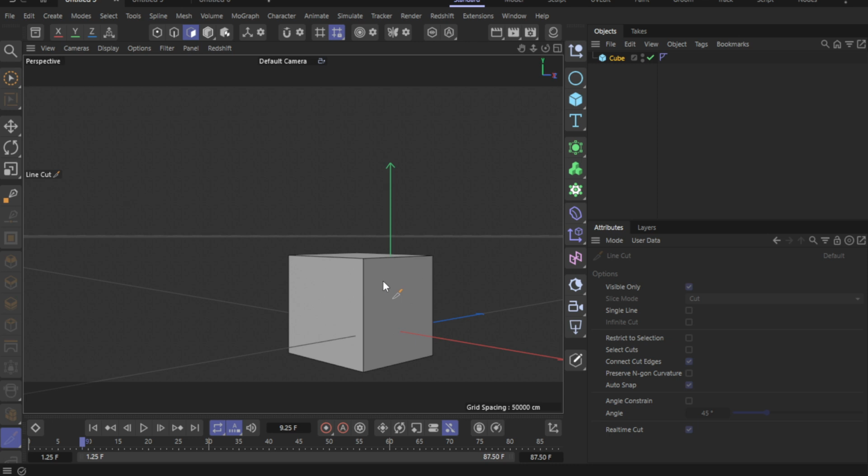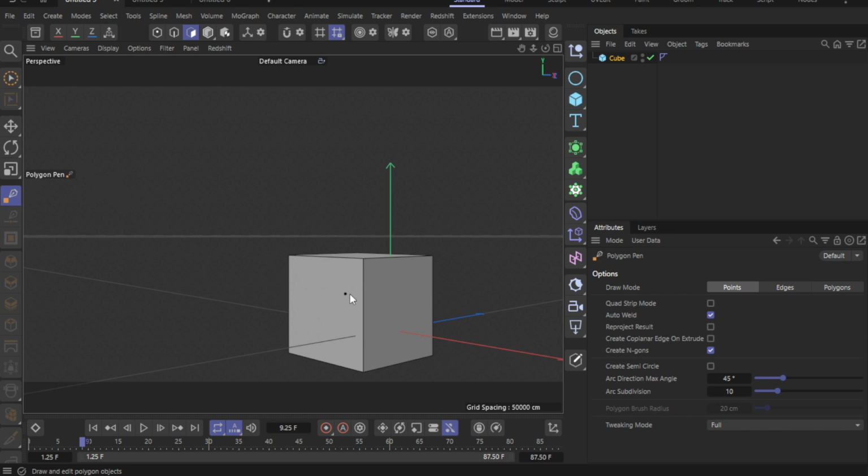You'll see the spline highlight and a live projection will appear across the surface of your object. This preview shows where the cut will run, taking the spline's shape and wrapping it over the visible geometry. Adjust your camera angle to ensure the projection hits the surfaces you intend. A clear view helps avoid accidental cuts on the wrong side.